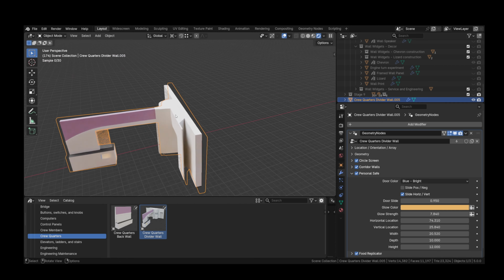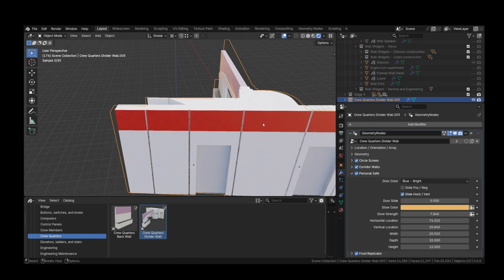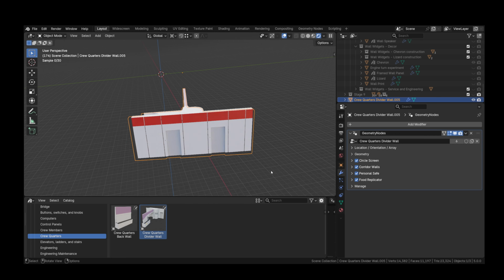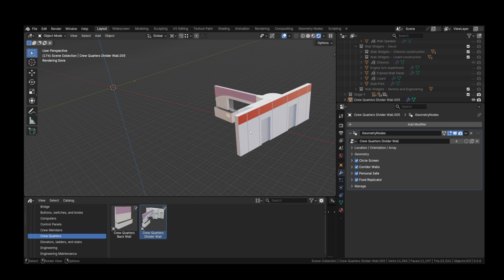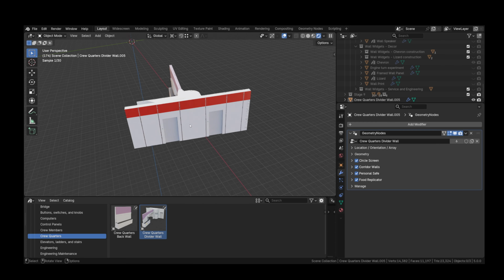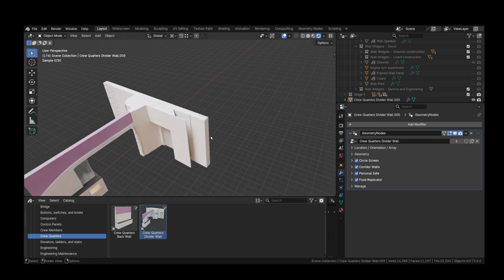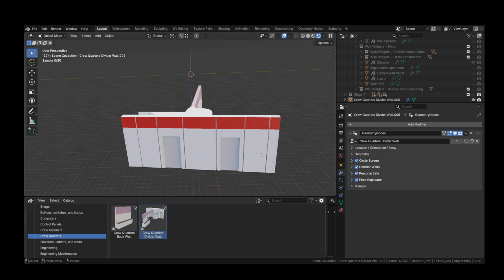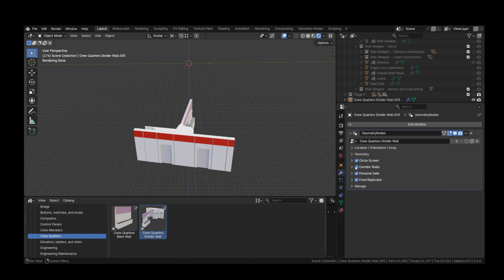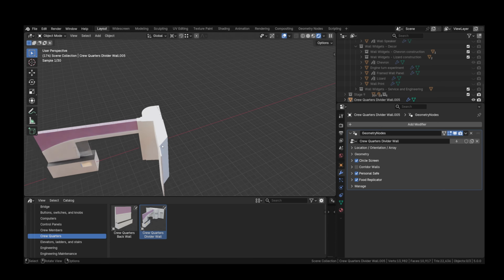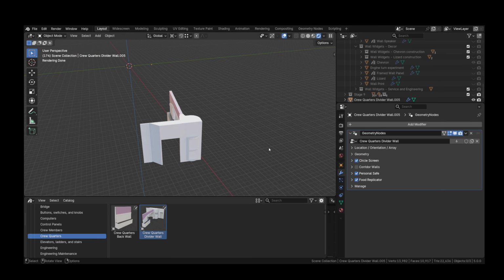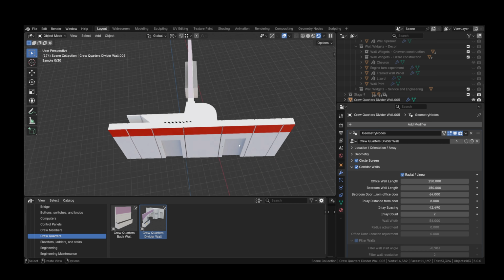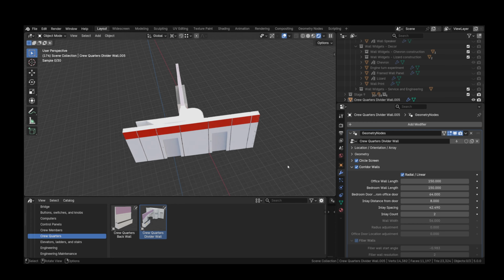Now this divider wall here also has the capability to integrate in the corridor walls here. That's to just make things a little simpler to set up when you have some radial walls that come in. And instead of having those independent and having to adjust those separately, I built those in. But if you want to add those separately, you can just turn the corridor walls off. And you could just have your corridor come up here and put those in individually if you want. But if you want to use the integrated ones, you just turn those on or off.